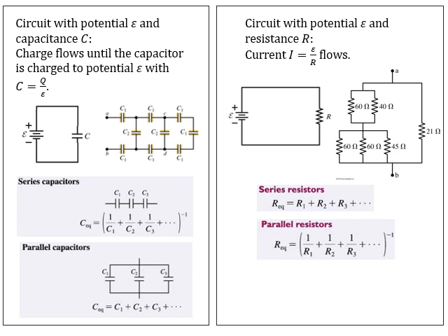Maybe the main thing to take away here, the thing to remember as we're doing our circuits, is that a circuit with resistors and a battery has a steady flow of current. A circuit with a battery and a capacitor will have a changing current while the capacitor is either charging or discharging. So that's going to be the foundation for what we talk about.